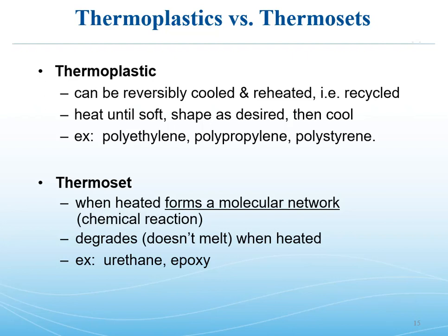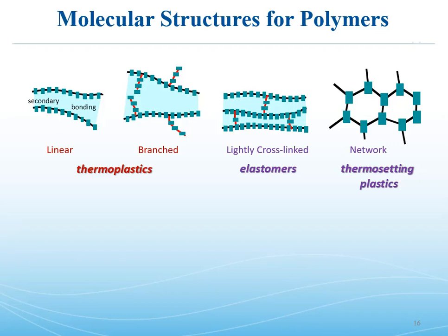That has big consequences when we're talking about the volume of polymers that we use in everyday society. On the other hand, there are selected applications where the properties of a thermoset are necessary for the given application, so they can do the job that thermoplastics can't in a lot of cases, so use judiciously. Several types of urethanes, not all urethanes, but many types, are thermosets, and most epoxies are thermosets, just for example.